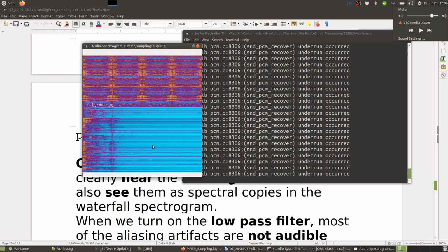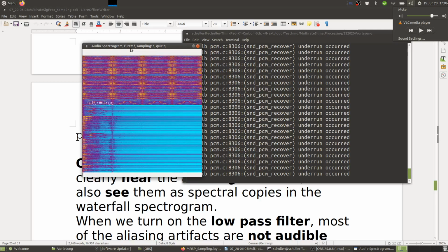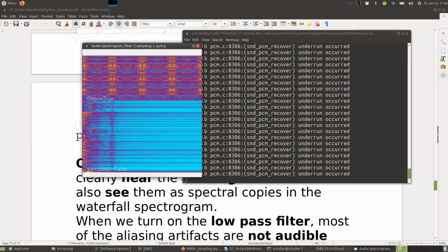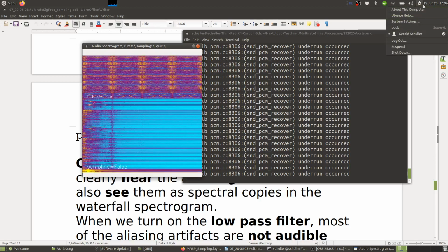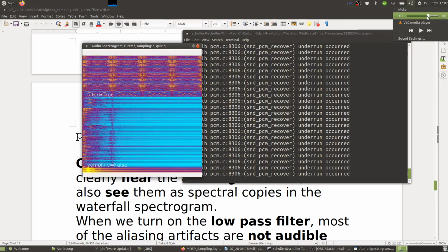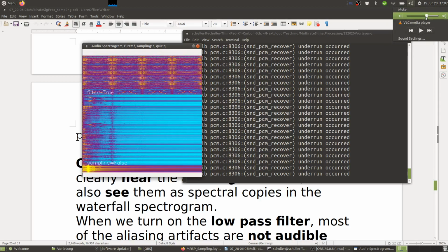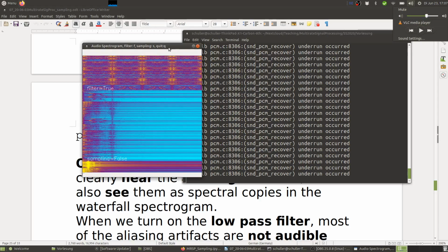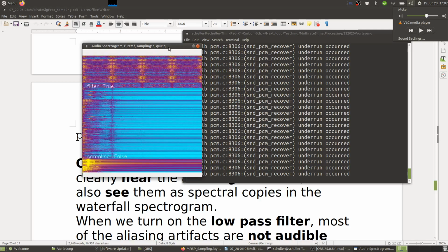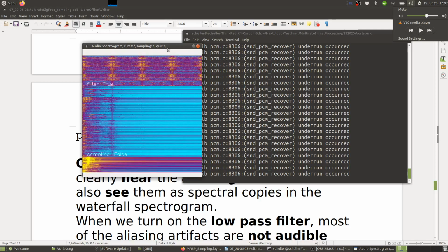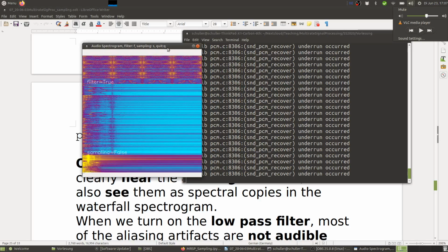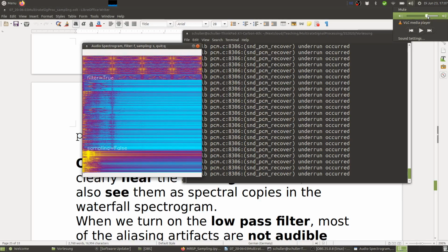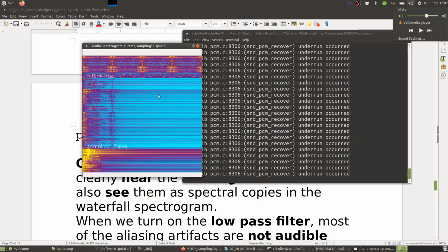So sampling off. First I have to activate this window, then I can switch it. This feedback comes because I have too much energy from the microphone directly into the speaker. Then we get this feedback at the beginning, the system begins to oscillate like an IIR filter, infinite impulse response filter. So when you have too much feedback, you get an oscillating system.